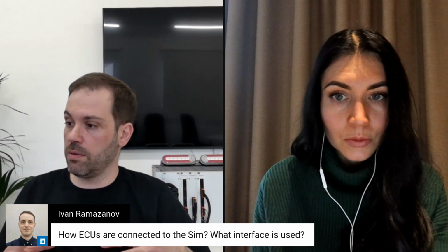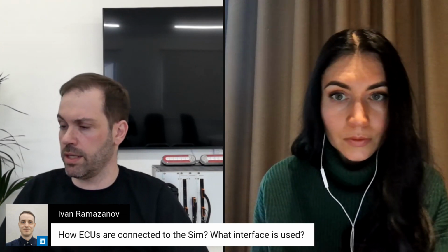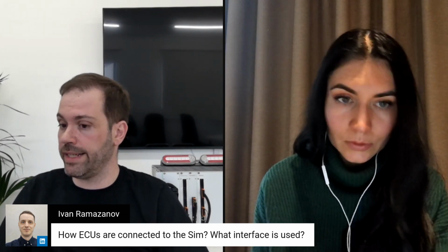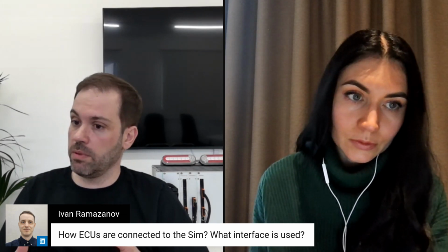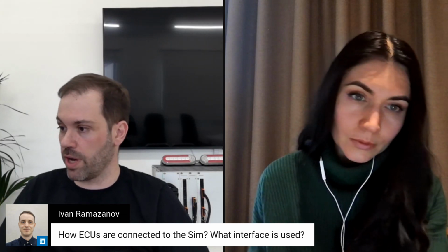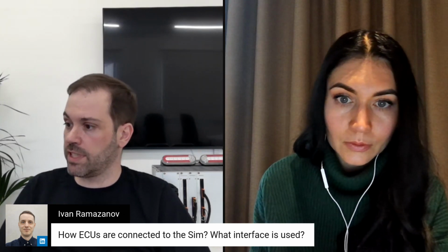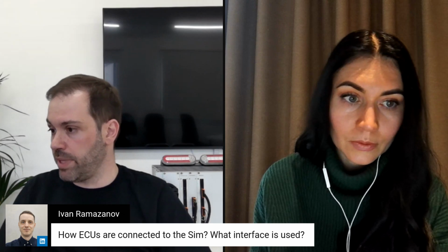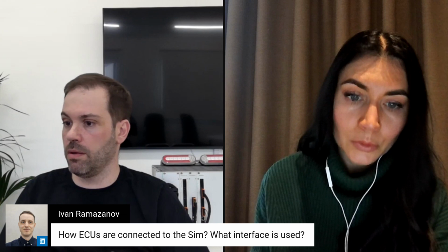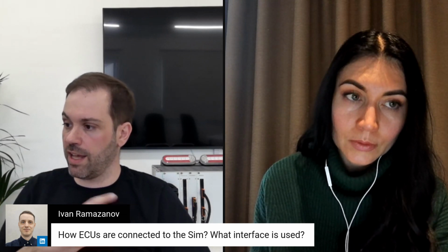The SIM has a lot of virtual buses like analog and digital inputs and outputs. It has CAN, LIN, and any kind of networking-based interface like ROS2, and all of those are part of the same virtual bus and can be connected between them. The SIM also supports connecting physical CAN devices directly, like PCAN, a Vector CAN device, or Quasar. So we can use a combination of physical and virtual devices to connect the SIM to both physical and virtual ECUs.